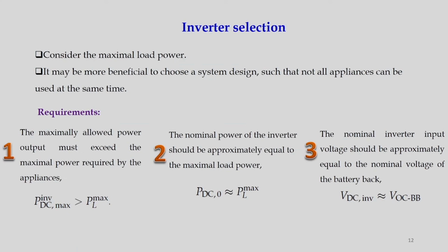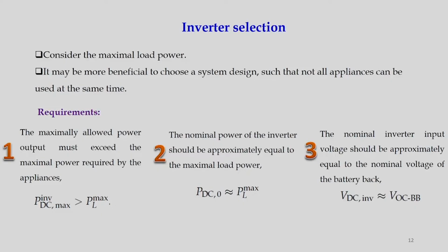Now, a very important factor is the selection of the inverter. While selecting the inverter, we must be very particular. This inverter should meet some requirements. Number one, the maximally allowed power output must exceed the maximal power required by the appliance.